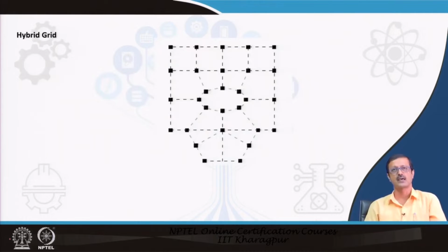But sometimes we may have some kind of hybrid grid. Suppose the orientation of our building is such that there is a circular atrium, but the building is very much perfectly square or rectangular, and there is something projected out which is hexagonal or something like that. So, in the hexagonal part I have to go for the oblique, in the central cutout in the atrium portion I have to go with the circular grid, and then from the circular it will go to some kind of oblique and then finally to a rectangular grid. So, sometimes you have to create those kinds of bindings from the column. How the column is binding all the different parts of the building is very much essential.